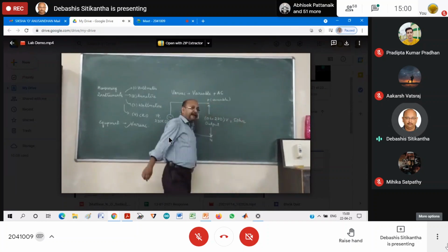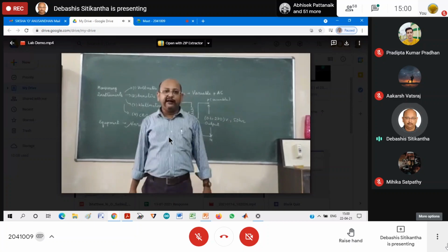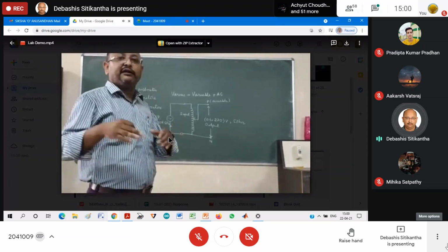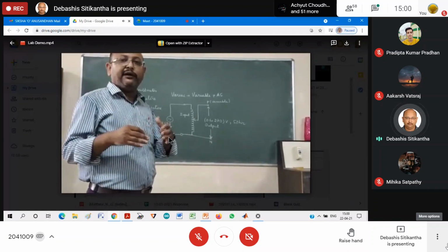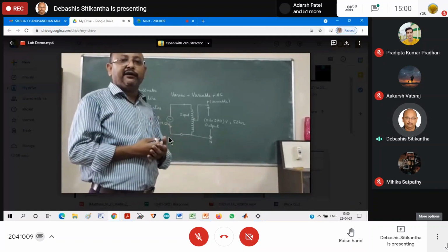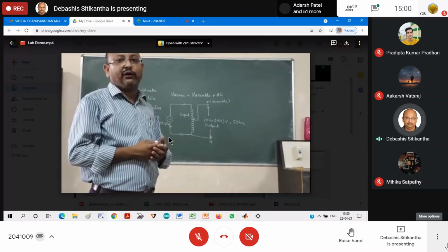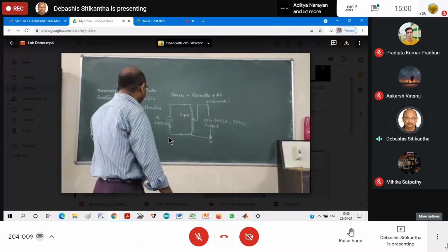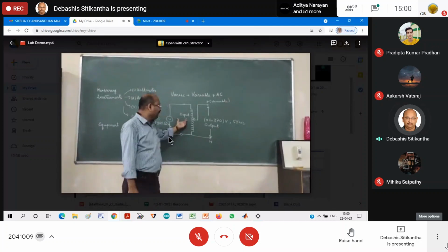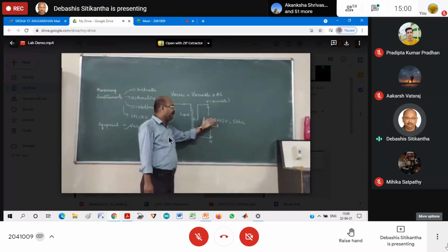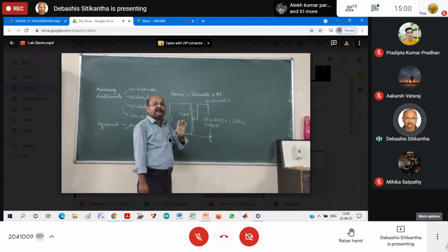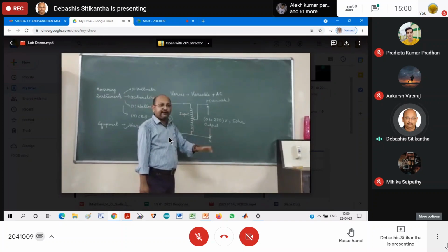Basically, the variac is going to behave like a variable voltage source. It changes the level of the voltage that I want to draw from a constant voltage input. The input is constant at 230, and on the output I am going to get from 0 to 270 volt. Always remember, this only works for AC signals, not for DC signals.